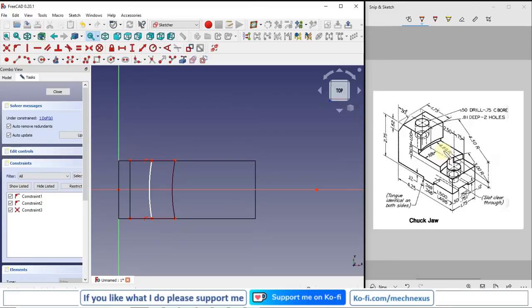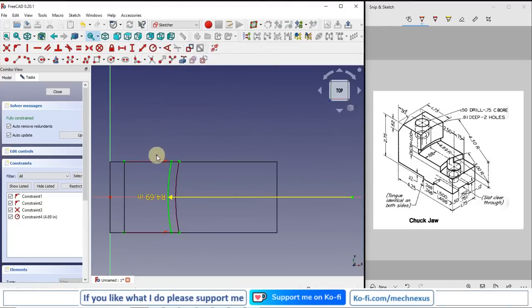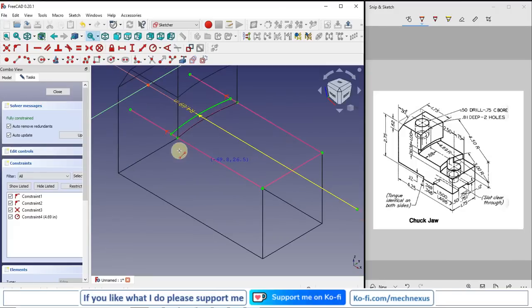And now the dimension is 4.69, so I will select it and I will give radius 4.69. And now I will switch to the isometric, and I will project these three edges, and I will close my profile.